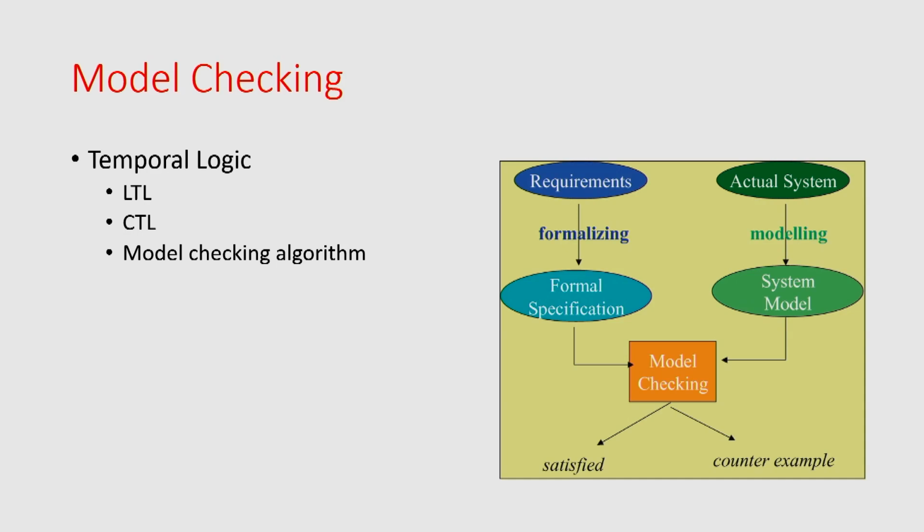On the other hand, model checking is another way of formal verification, in which we do things in a different way, right? Here you have the specification or the system. You have the specification, you identify the properties, okay? So you need to identify the correctness properties, and for that you need temporal logic, okay? It can be linear temporal logic or computation tree logic, right? So it's called LTL or CTL. We will talk about them again in more detail. So let's say I have this temporal logic through which I can write the properties of my hardware, okay?